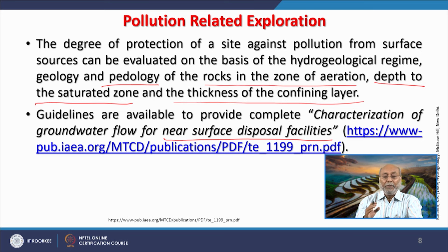So, as soon as people realized that there is a problem, that these ash waste disposal sites are creating pollution in the groundwater regime, then at least new sites were selected where a lining of thick polythene is being put. Special polythenes are coming. So first you line the bottom of that pit at the base, and then you start putting these things. But somehow you have to think how to recycle it, otherwise you would be requiring a large area.